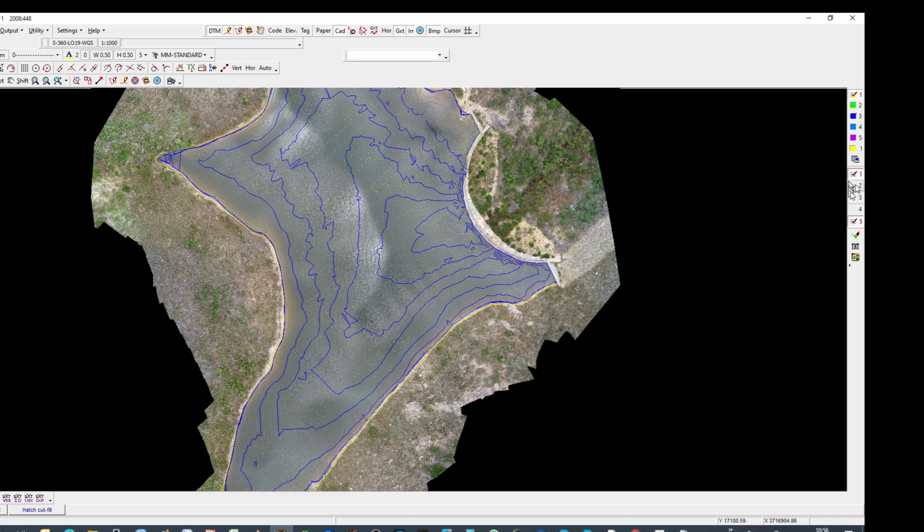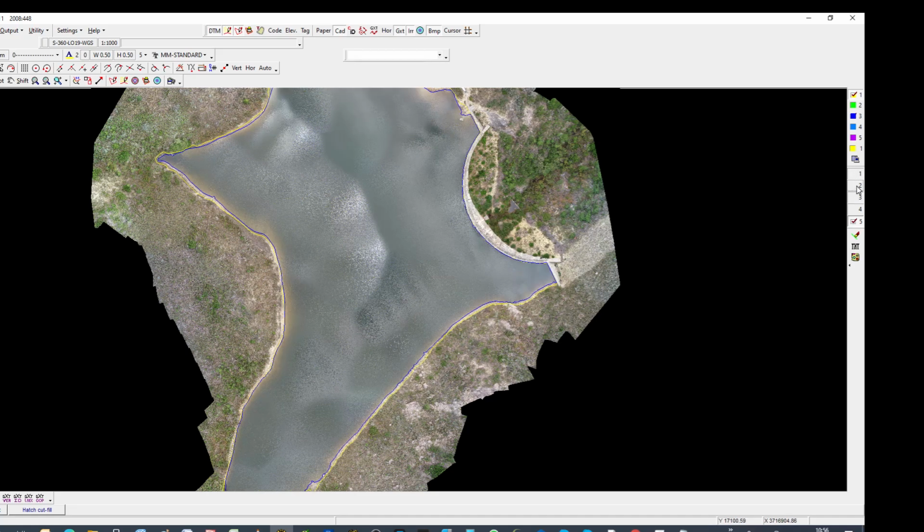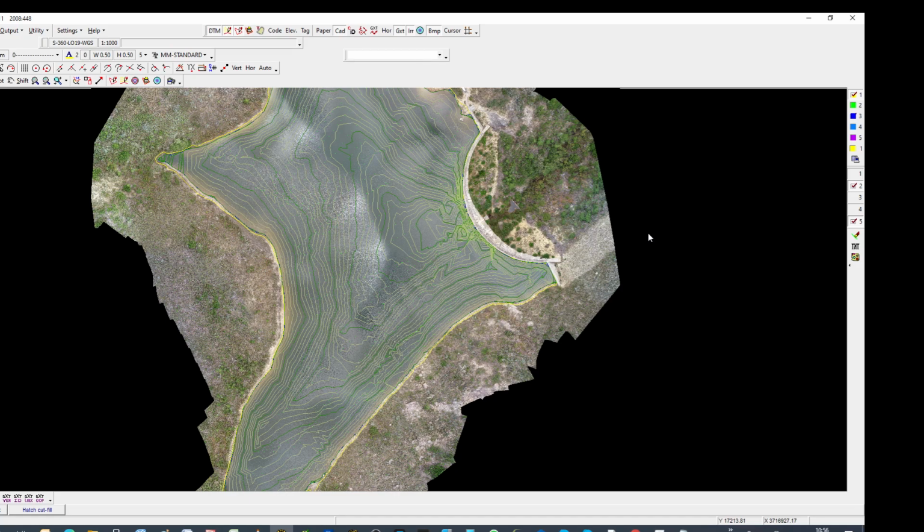We have the 15 degree and the 55 degree cone. The 15 degree will actually penetrate through to the hard bottom, and the 55 will pick up vegetation and an apparent silt level.